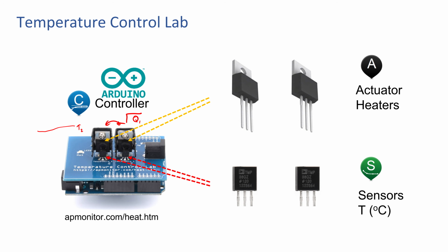So you've got heater 2 and temperature 2 here. And then on this side, you have heater 1 and temperature 1 as well. Okay, so that was the linear model predictive control with the ARX model. There are other labs there that show how to use machine learned models to do the control applications, as well as these linear, statistically identified models, or you could also have a physics-based approach to this temperature control lab, as is shown here.